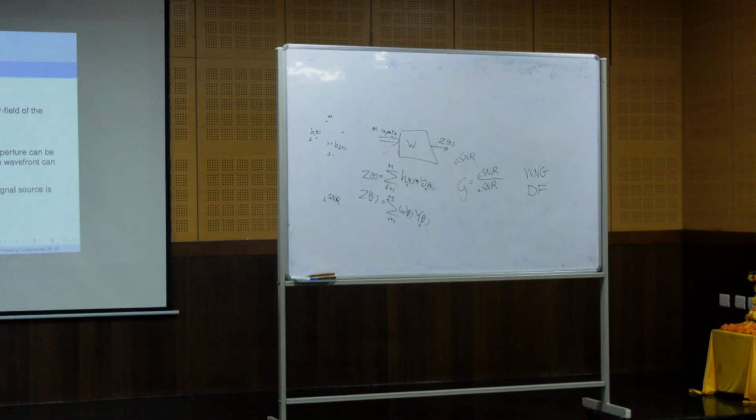So for far field, we have that the distance of the source is much larger than L squared divided by lambda. But if this is not satisfied, it means that the desired source is in the near field. Okay? And for far field, we can assume that the source transmits plane waves. But we cannot approximate the source signals as plane waves if the source is in the near field. So we need to change the plane waves into spherical waves, like this.